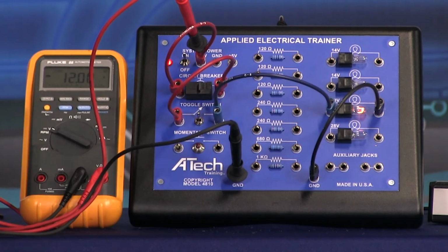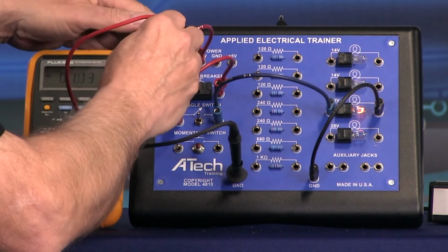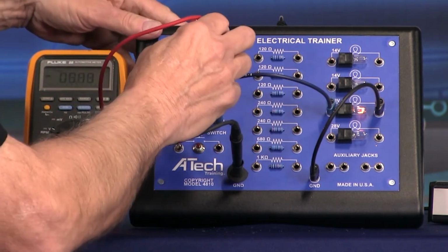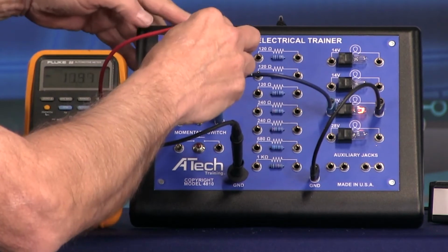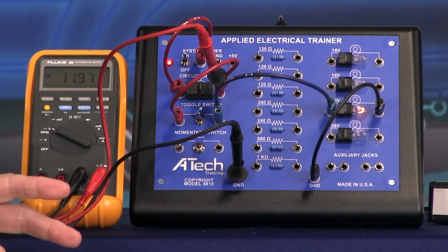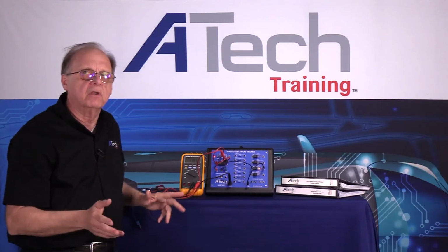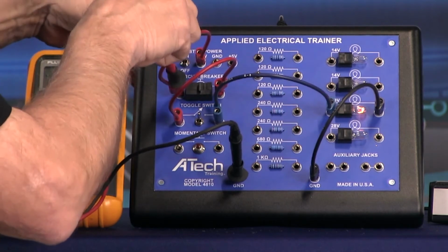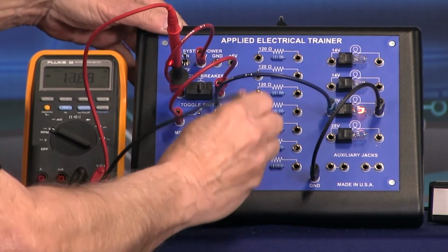Notice the light's on, it's dim. I still have 12 volts, right? I got 12 volts there. I'm still doing the same process, doesn't make a difference up there. And notice that this one, I got 11.97. So that immediately tells me that I have more resistance in the circuit. So what I'm going to do right now is voltage drop this device and have some fun with it.